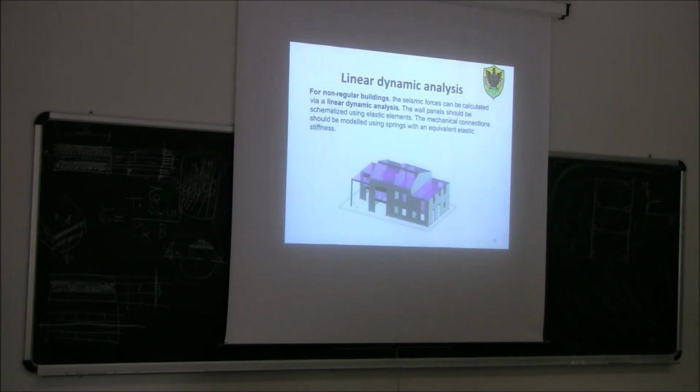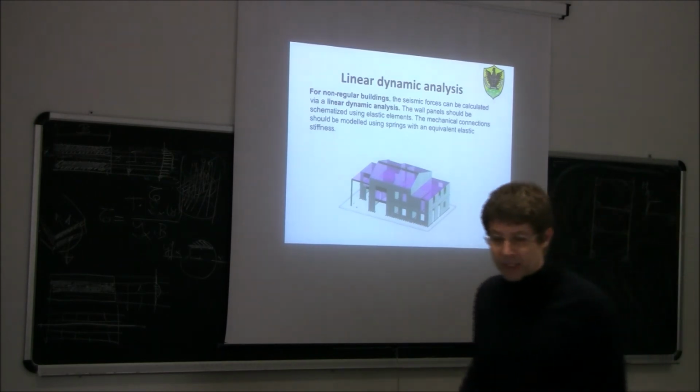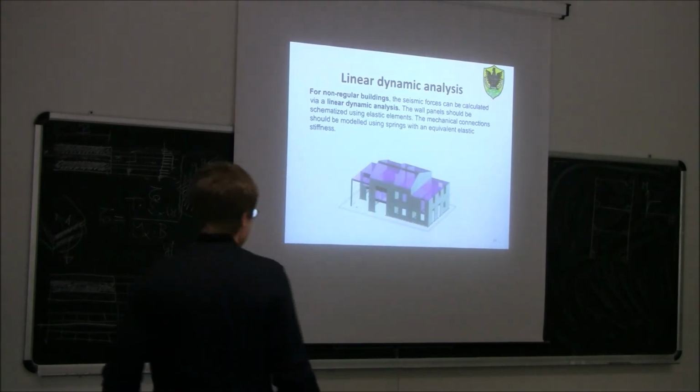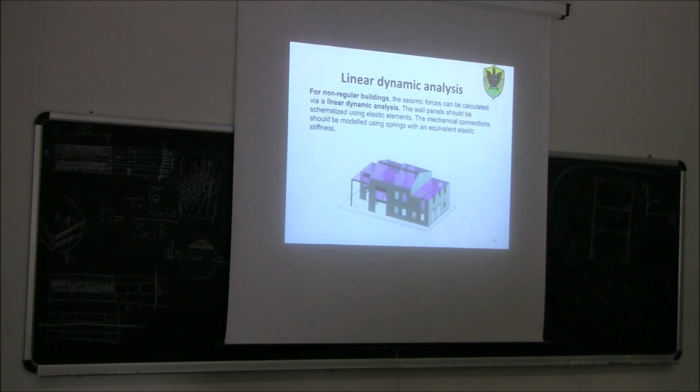And this is actually mandatory if you have non-regular buildings. So if you have a non-regular building, we need to use the linear dynamic analysis, which is more complex and which can be done basically using only software.